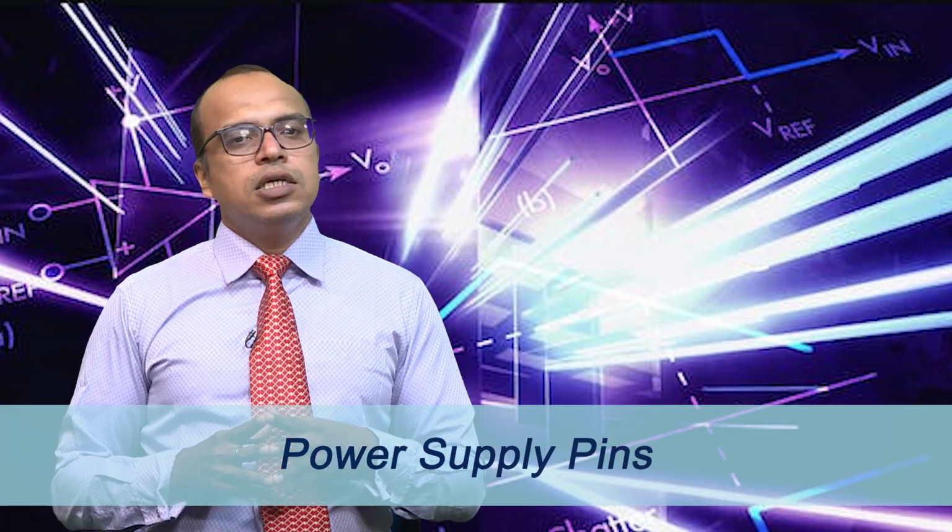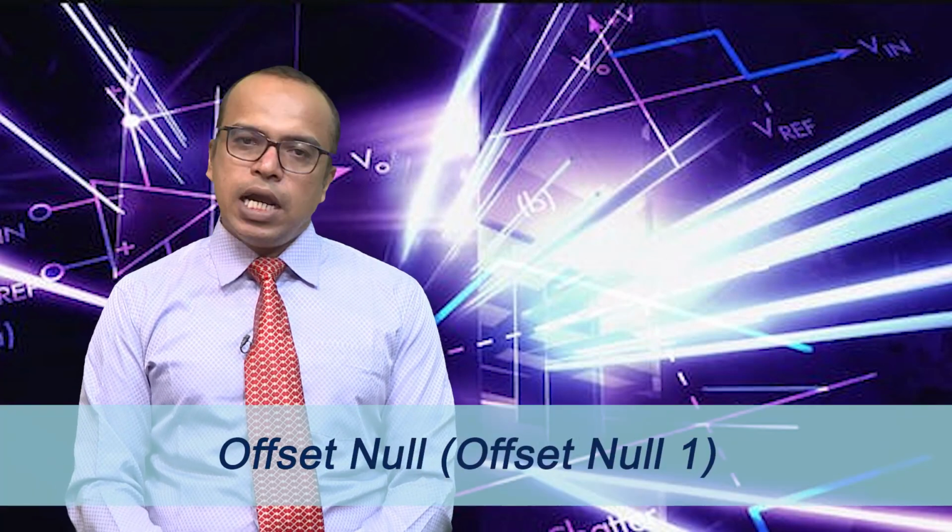Power supply pins. In the circuit symbol you may also see power supply pins represented as VCC and VEE, or VCC and ground, depending on whether the op-amp is powered with a dual supply configuration, positive and negative voltage, or a single supply configuration, positive voltage and ground. These pins provide the necessary voltage level for the op-amp to operate. Lastly, offset null. Some op-amps may have additional terminals for offset null adjustment. These are used to fine tune the output voltage to 0 when there is no input differential voltage. The terminals are often labeled as offset or offset null.